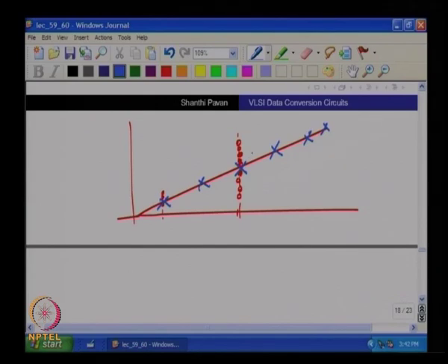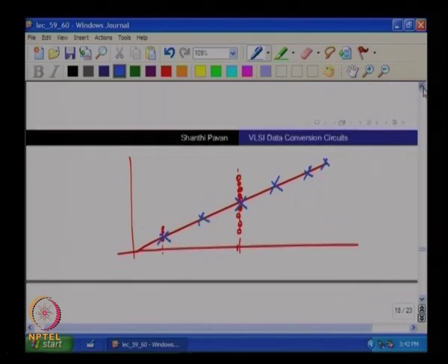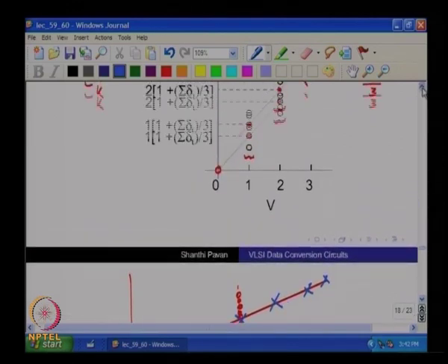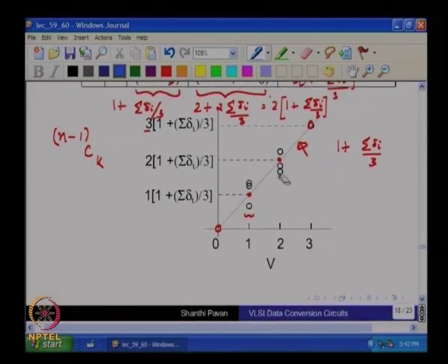To give you some intuition, ideally, if you use the thermometer type decoder, your DAC would have the same element every time. So, the characteristic of the DAC would probably be some nonlinear thing like that, correct. Then the obvious thing is to say, on the average I want a straight line.